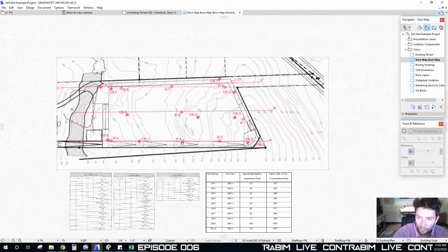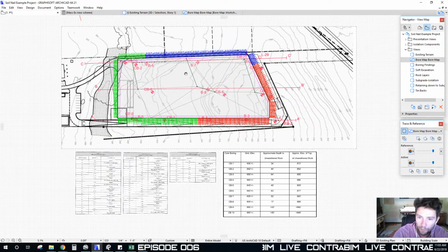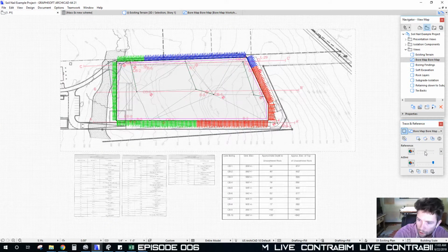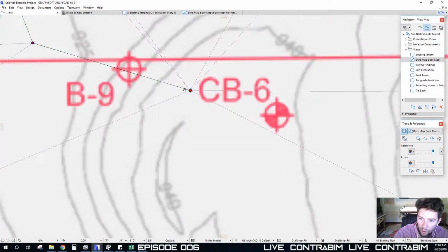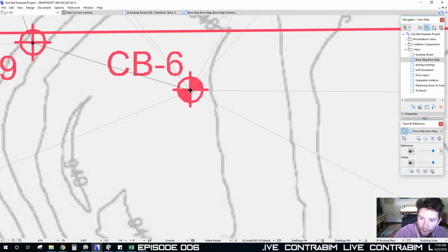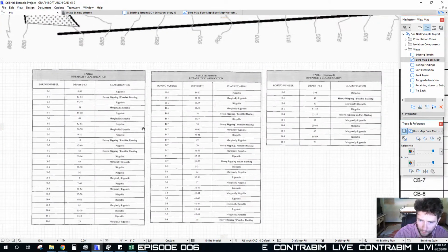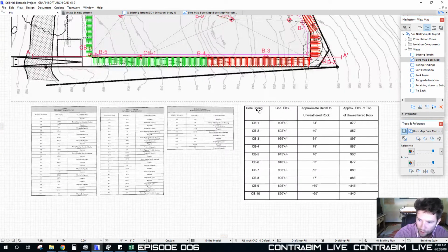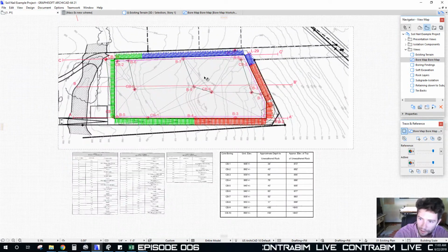From these boring maps, if I go to my floor plan view here, we can turn on that boring map as just a reference. Then we can start dropping in individual columns and using the depths found from the different surveys performed, and use that to map out the depth, in this case to the rock.